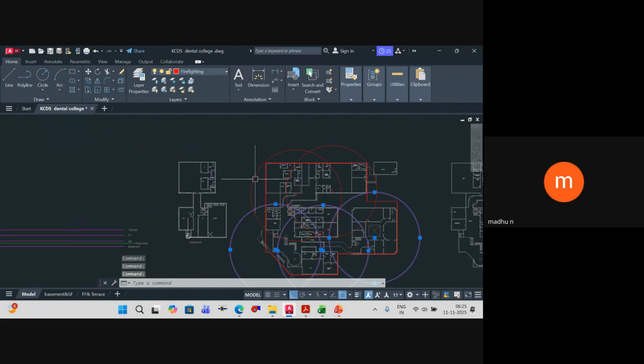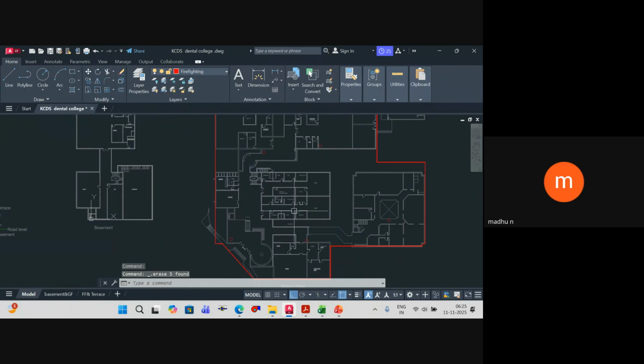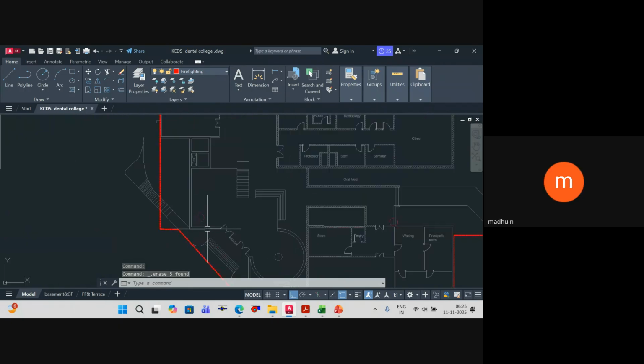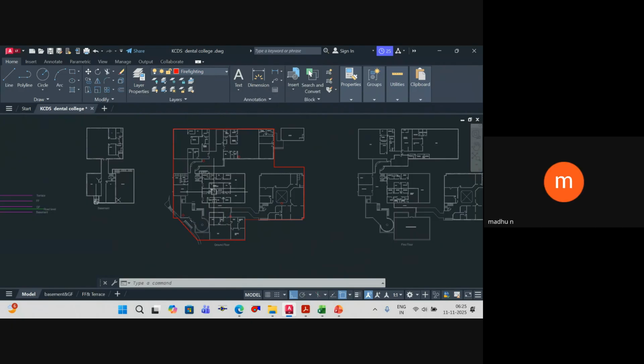Is locating the hydrant close to the exit or entry applicable to all the hydrants? No, not like that. For the main entrance only, you have to consider. Near the main entrance, you have to provide. See, one aspect is, let's say once a firefighter has come into the building, if you keep it away from the entrance, then will you be able to access it easily? No, you might not be able to notice it also.